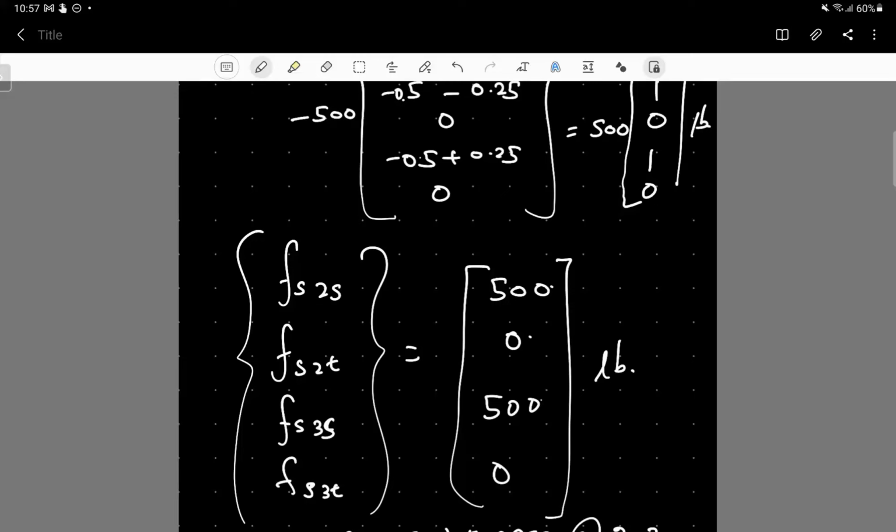Since we are almost at the end of the lesson, I think the time will not permit us to discuss the Gaussian integration scheme. Why we need to discuss such an integration scheme is that, in order to evaluate the stiffness matrix using the isoparametric formulation, there are two integrals that need to be solved. For this, an integration scheme is necessary because there are no direct solutions, so numerical integration schemes have to be employed. The most commonly employed scheme is the Gaussian integration scheme.